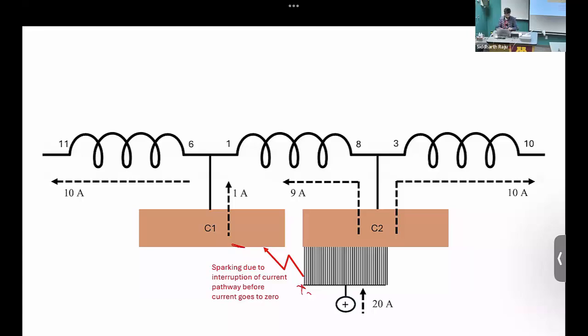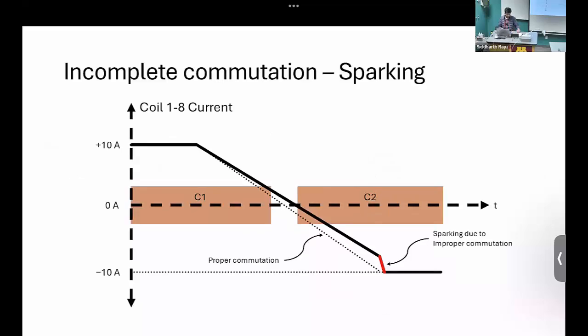And that will start to damage your graphite brush, because every time ionization happens, there is going to be carbon that gets oxidized and starts to break down. So carbon is going to get broken off. And that vapor graphite is then going to settle on these copper brushes and in between these segments, and over some time period will start to short out the whole commutator segment, right? So this is improper commutation.